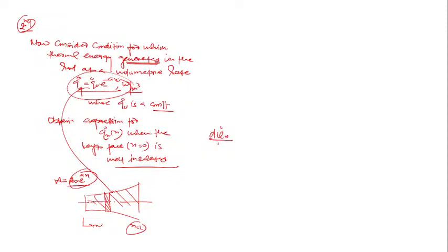Look what will happen. Again we should use a small differential element, and from this differential element I get a differential equation for dq dot x. But this time a heat source is there, so we should go for the balance. Then I should write q dot x minus q dot at x plus dx plus qg dot as a function of x into volume. Volume should be dV. dV is what? Area into dx. Area at x into dx. Yes or no?